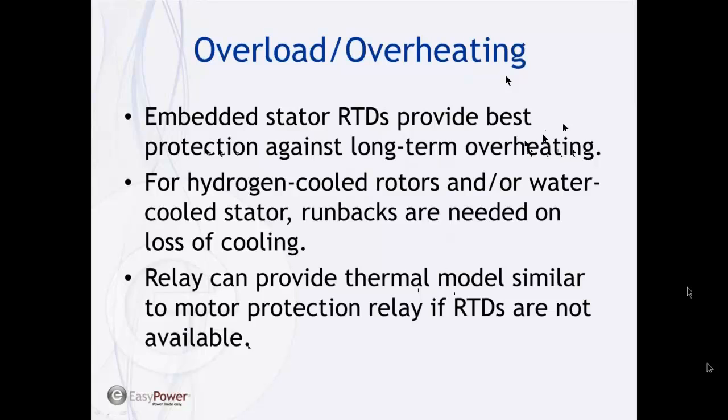Now, if you don't have RTDs, the relays these days can typically provide a thermal model similar to what we do with motor protection. So that would be another option, although the actual temperature measurements are going to be your best protection against actual overloading or overheating of the windings.